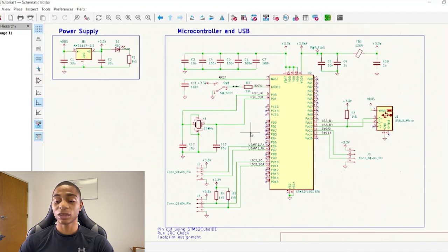And this line is used for transmitting and receiving data, so to and from our microcontroller. So it'll all be on the same line. And then if we want to go over what serial is, it means that the data will be transmitted sequentially, bit by bit over that line, so one by one.